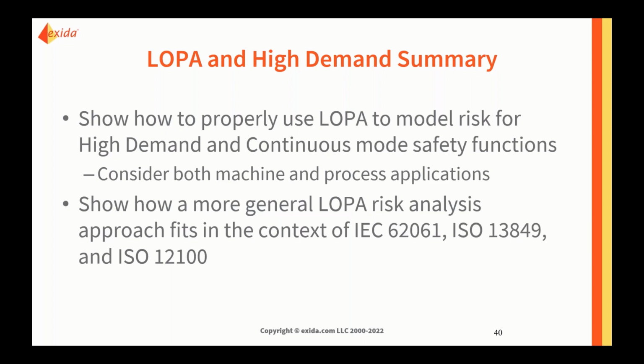All right, now I've got a few other questions that have come up that I haven't taken on quite directly, so let me take some of those at this point. So I've got a series of questions that says, first, when a risk matrix is used for SIL selection, how can we select high demand mode? Well, the risk matrix, if it has the SIL in the boxes, that is inherently a low demand mode technique.